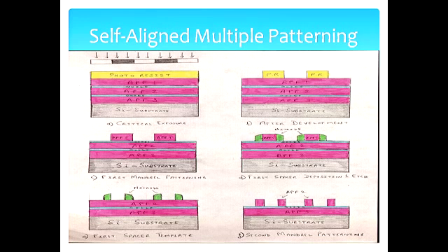So given lambda, you said it stagnated at 193 nanometers. What's the smallest feature you can make with this method right now? Oh well, according to my equation, it could be anything. It just depends on the number of layers you use. But what's the practical one they've achieved? Practical, as of now, it's stalled at quadruple, so you can go up to 4 times that of what's on the mask. Okay, so you basically can go to maybe 25 nanometers, 30 nanometers.